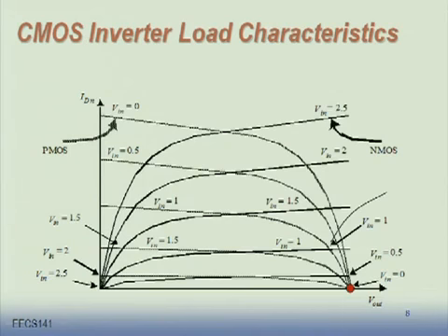When V in is 0.5 volts, it's a little bit less than 2.5 volts. I'd say 2.4 something. When V in is 1 volt, it's like 2 and a change. When it's 1.5 volts, whoa, it's all the way down. So it has passed the switching. It went through this high gain region and went down to about half a volt and continued going down.